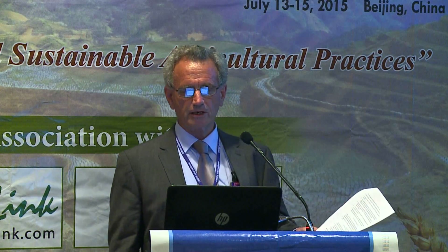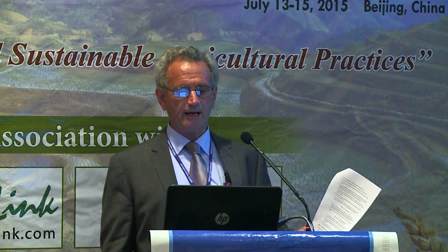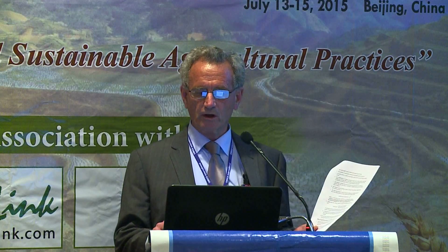I'm now going to discuss some of the advantages of this particular model of unpowered evaporative measured irrigation. I have a total of 9 advantages. We'll go through them one at a time. Firstly, you save more water by controlling the application rate for each plant during the hottest dry months of the year, taking account of all relevant factors such as evapotranspiration, soil type and leaf area.